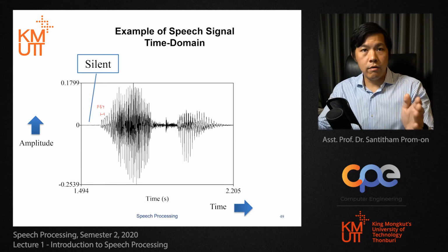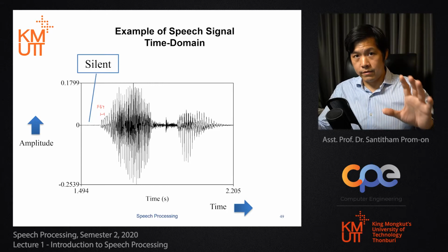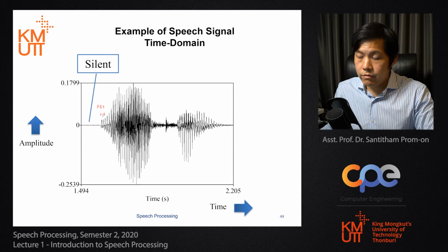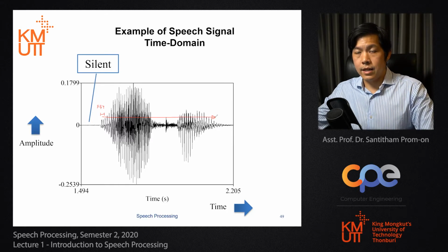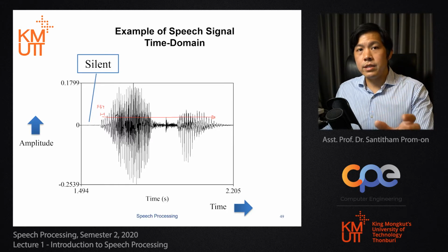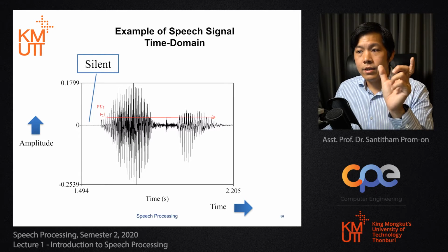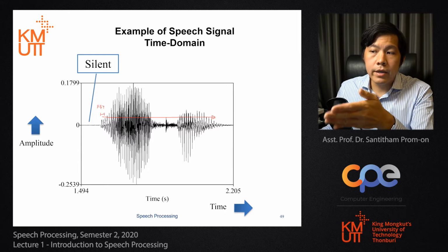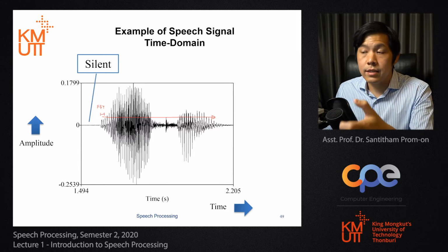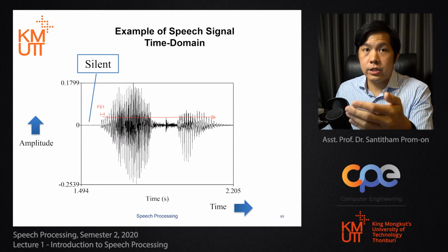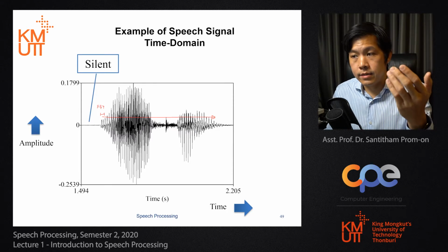So you know the spectrum content of this short period. And if you move this window throughout the signal, it will analyze the frequency content of small parts of this signal, so that you know that at this time point there is this much frequency in this specific window, and it will change according to the time point that it occurs.